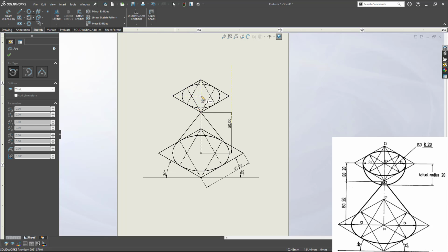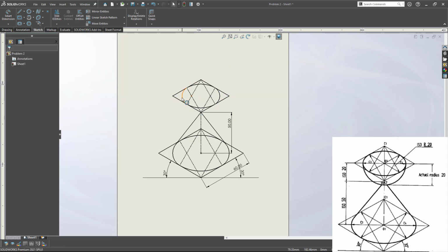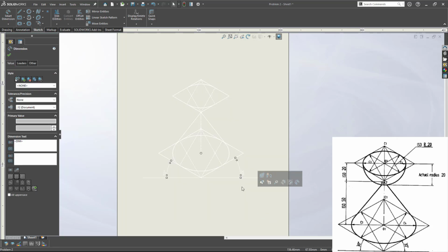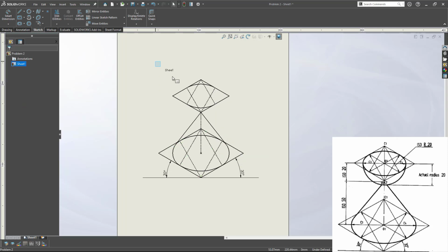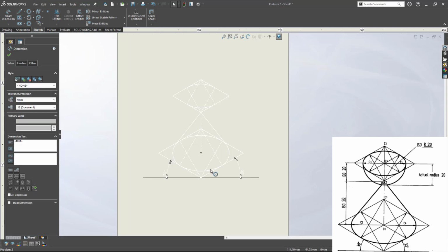So from this is the center reference, and here if I try, it is 23. So in the sense this point is not a proper one. So what you can do is you delete these two at the moment. I need to scale entire thing. So for that what I will do is I'll just remove this dimension at the moment, delete this and delete this. Now you can select everything except this and then simply right click. Sorry, why I'm doing it here right now, because these all things will be with respect to isoscaling.